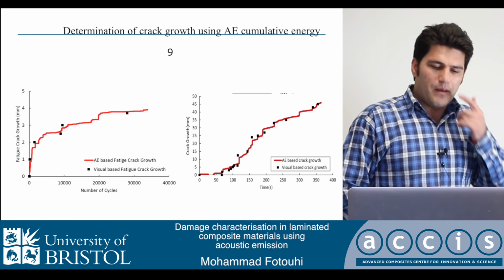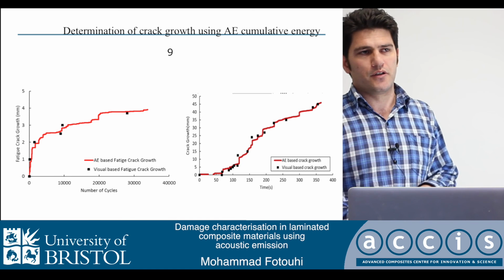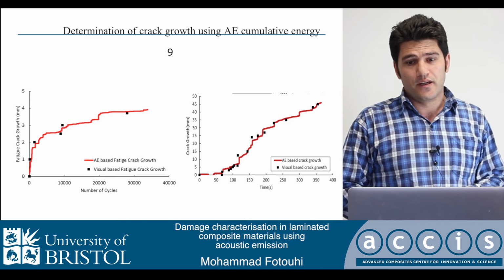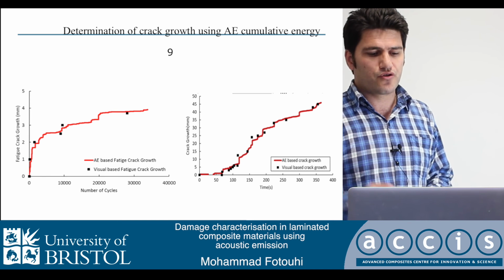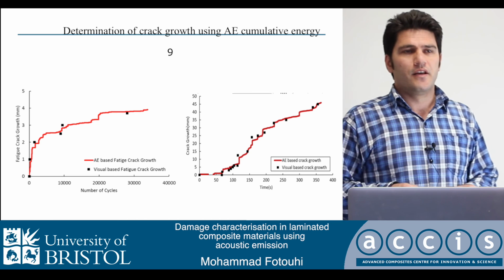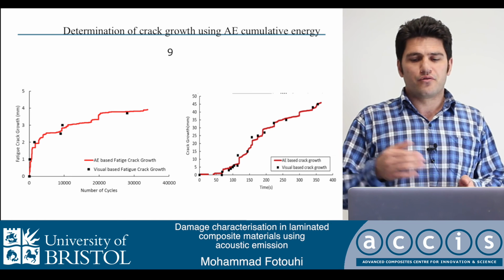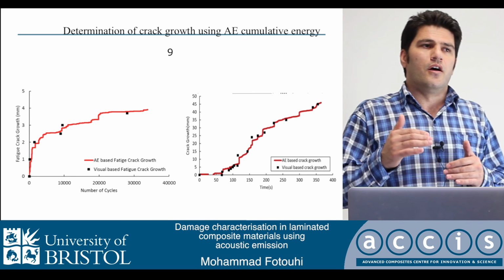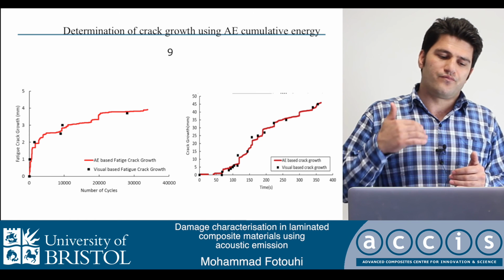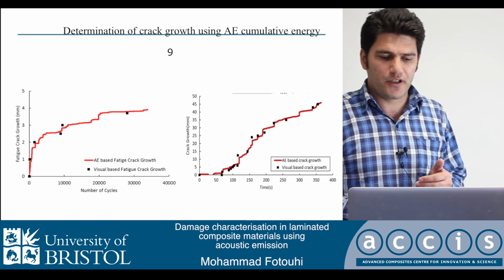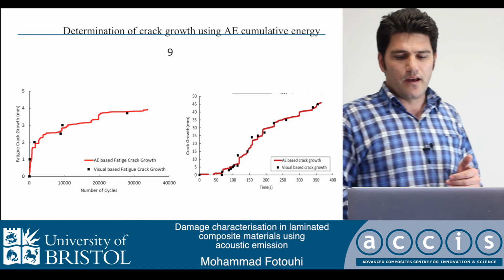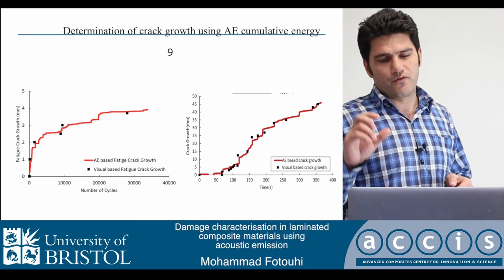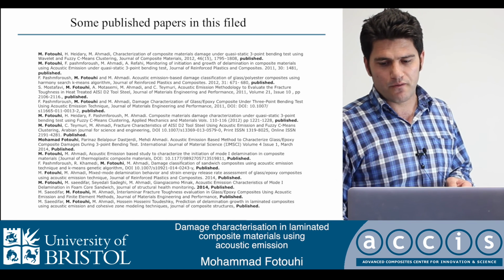Another application of acoustic emission that we did was following fatigue crack growth. We followed the fatigue crack growth using just acoustic emission, and we found that we can use acoustic emission to follow and measure the lengths of cracks in fatigue and even in static tests. This is a very simple and useful method, where we can use one sensor that determines the length of cracks.